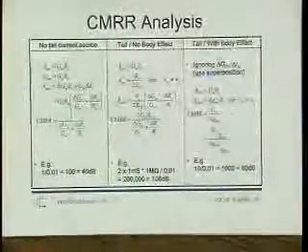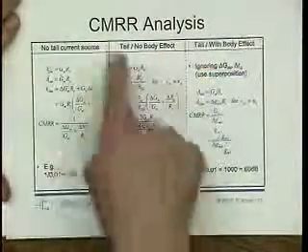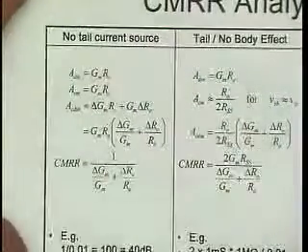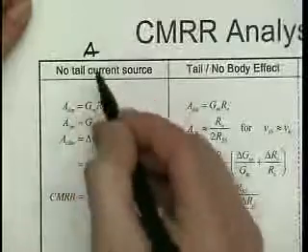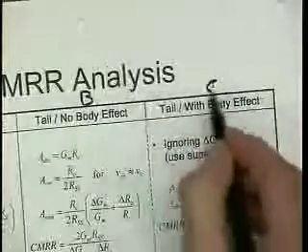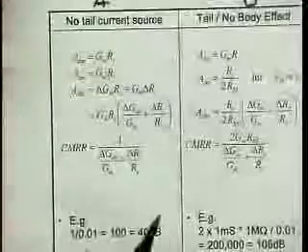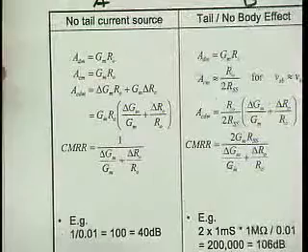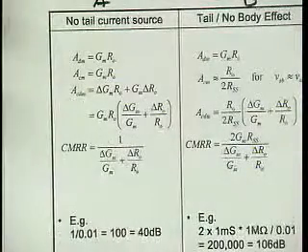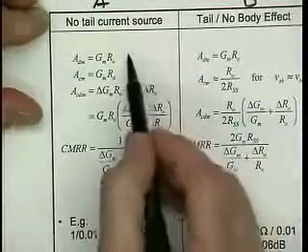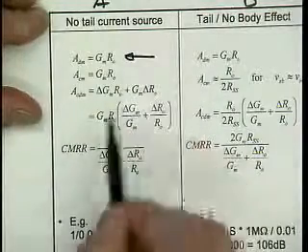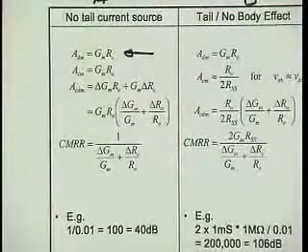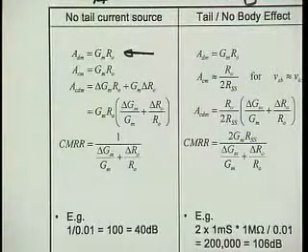Here I actually did some analysis. If you can use more zoom, I'll go through these one by one. So these are solutions A, B, and C, right? To calculate the common mode rejection ratio, I need to calculate the ratio between the differential mode gain and this ACDM that we defined last time. The differential mode gain, of course, is trivial, right? And then this ACDM, well,